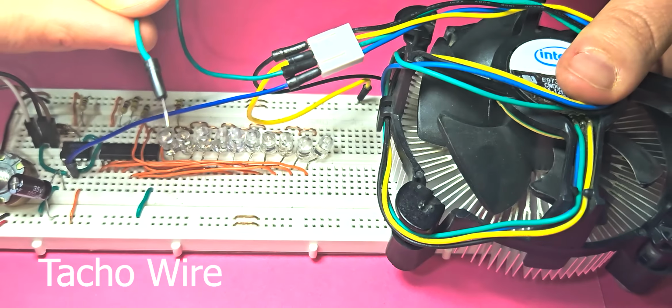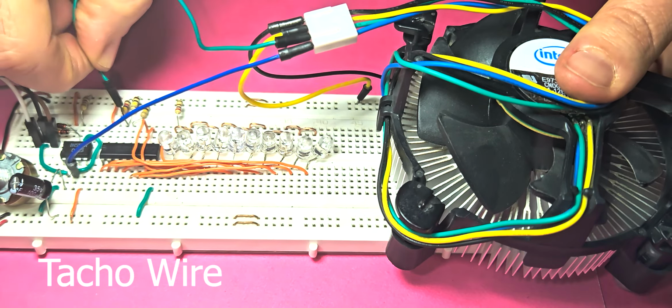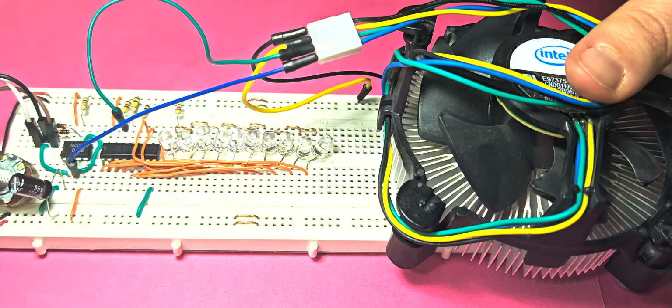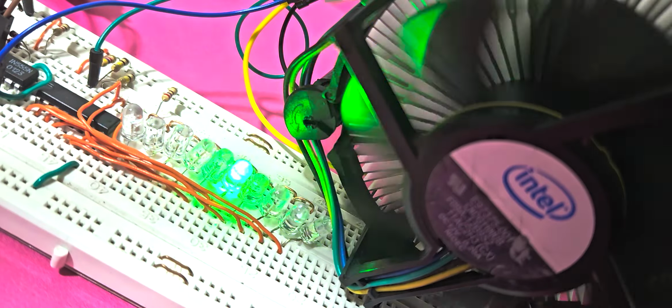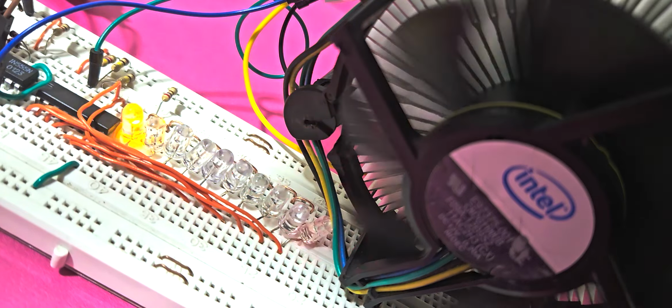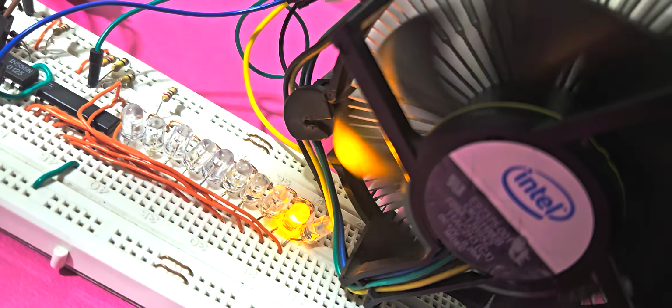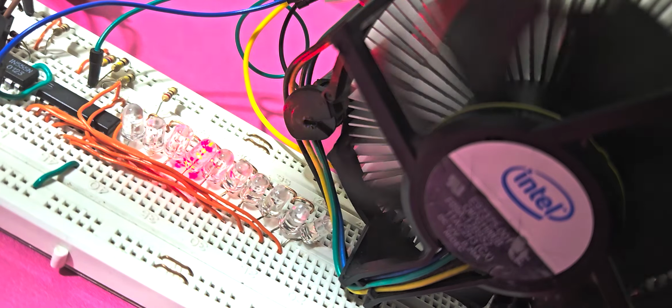In this circuit, the TACHO base is connected to the pulse input of the 4017 IC and applies 2 clocks to the IC with each rotation of the fan. The outputs of this IC are connected to the LEDs, so by applying the pulse, the LEDs will light up in sequence.